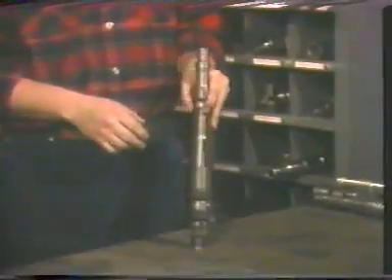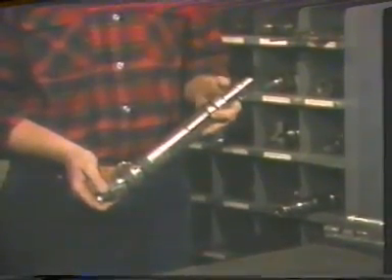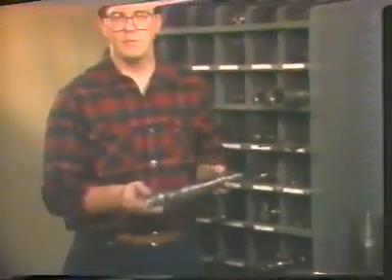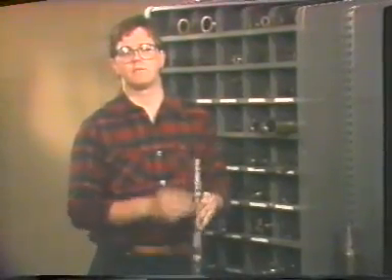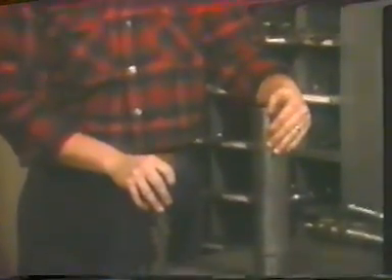The slip lock can be used to anchor plugs, safety valves, pressure regulators, or bottom hole chokes. These locks are usually limited to use in low-volume, low-pressure wells. This is because slip locks have a relatively small flow area through the bore of the lock and limited pressure ratings because the lock uses the tubing wall itself to anchor the lock, and the condition of the tubing will deteriorate with time. Most wells today are completed with future wireline work in mind and have a series of receptacles or landing nipples included in the completion string.